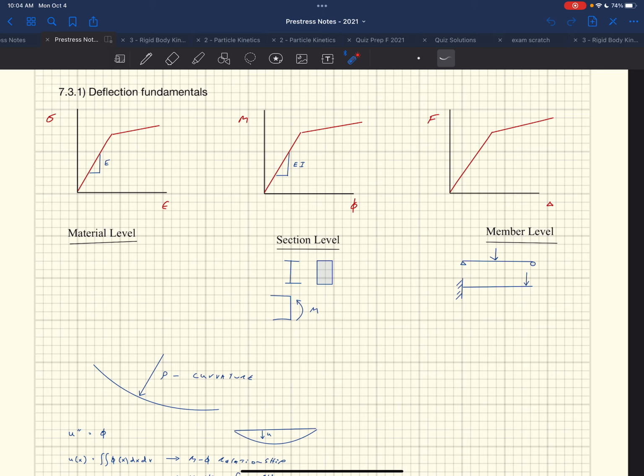And so you have 2 different strengths of concrete, and one's pre-stressed and one's not, and so one has pre-compression, and then the top slab that has no pre-compression, and how do you go about designing for those things and all the different loads. If you thought there was a lot of things to manage in terms of load cases before you added on a composite slab, you're in for a treat. There's like 10 more things we have to check once you add that composite slab on top.